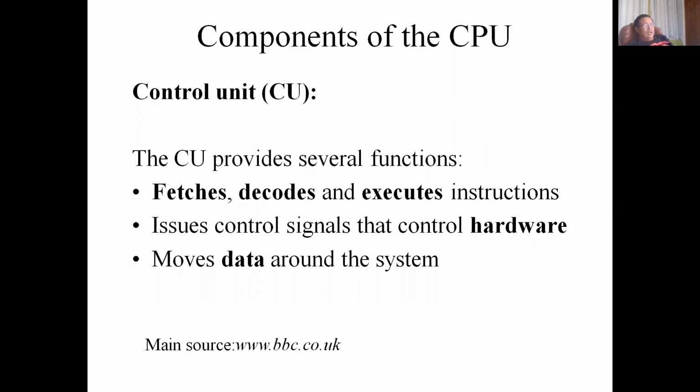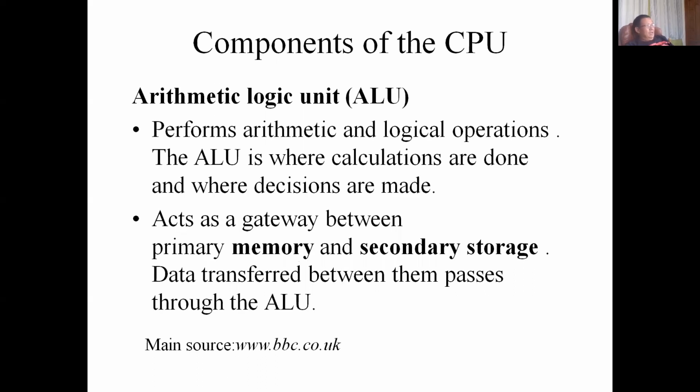It's the control unit that tells the arithmetic logic unit to add or subtract, that tells the accumulator to load or store. No? It moves data around, no? From register to register, from register to memory, like the accumulator. No? The arithmetic logic unit, we have seen this. It does the arithmetic and logic, like addition, subtraction, shifting to the left, shifting to the right, inversion, no?